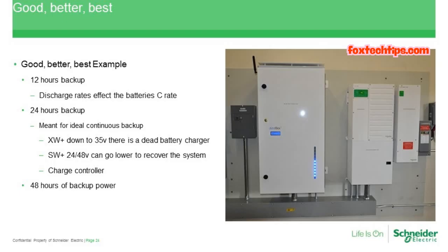If you do decide to add more solar at some point in the future, or want to do a battery-based system, again, to requalify for that tax credit, you do need to bring more solar in. And so definitely check with a tax expert, but you can't do it without doing solar. So if the customer is looking at doing a battery retrofit, the upside is that a little more AC coupling is going to be fine, and just make sure that you're sizing the inverter for that upsized system.